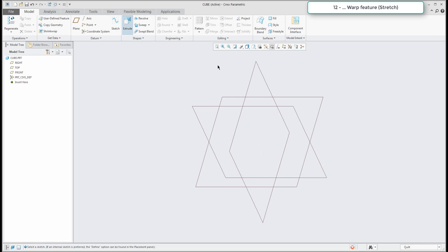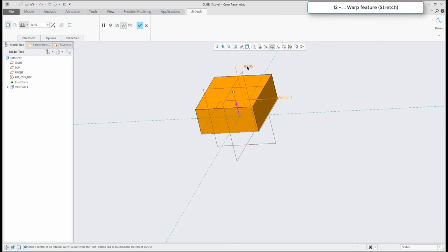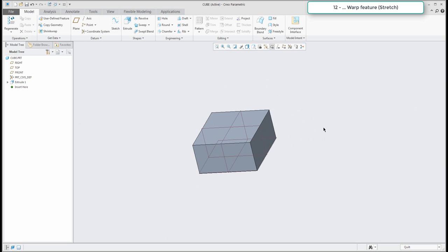You know that it's possible to create an extrude feature, but sometimes you specify your shape really quickly and set some dimensions. So for example, I will set this dimension to only 150, but the size will be only 75. Okay, it was the base idea that I would like to try to create the brick based on these dimensions, and then somebody tells me, oh, Vladimir, can you change these dimensions and extend this shape? I said, okay, what we can do is use a warp feature.